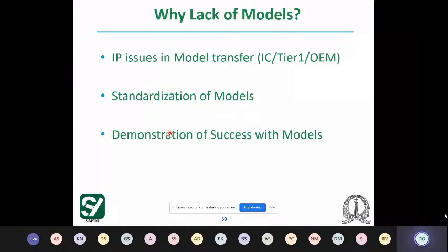Right, but then now let's talk about IC models. What are the challenges of the IC models? Right, first thing is that the semiconductor vendor has his own IP built into the IC, so he cannot really release the entire SPICE deck of the IC. And although IBIS has been there for a while, the SPICE file is ruled out. SPICE file will give you all the internals of an IC, and if it's a digital IC, then SPICE file, which is really for analog simulations, is just not manageable. SPICE can handle up to probably 1 million, 10 million transistors. Beyond that, it's hard to handle for SPICE itself. So digital design doesn't even do SPICE.